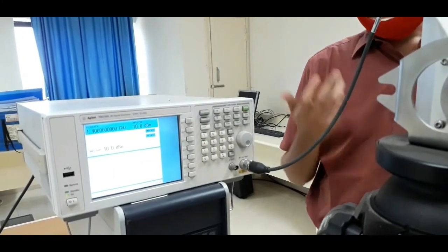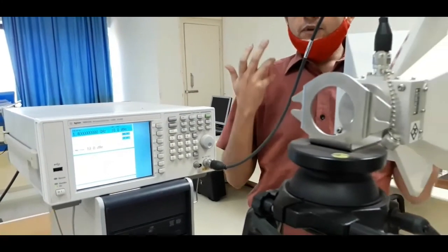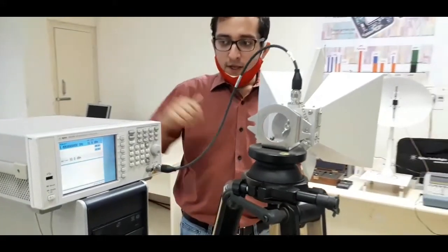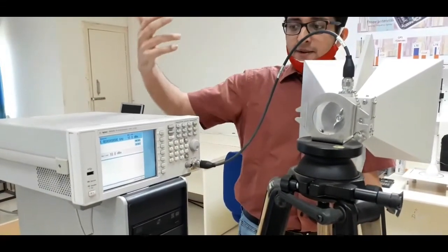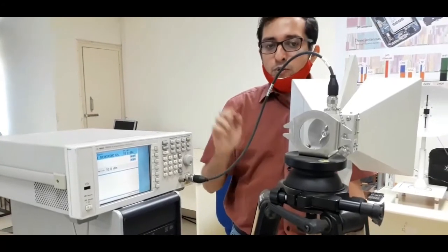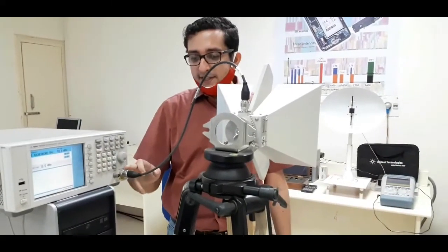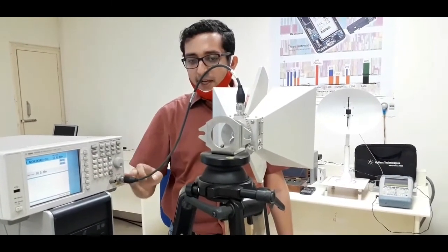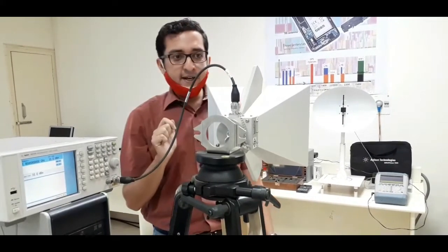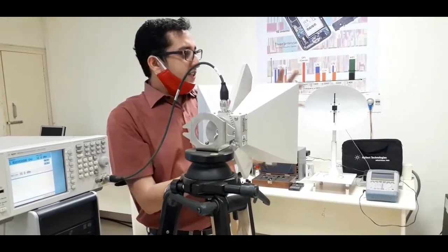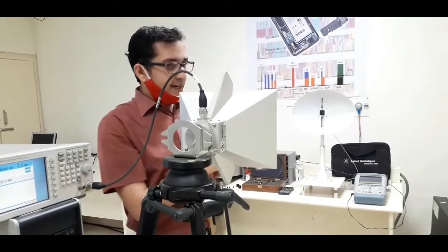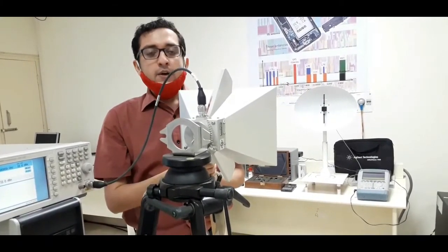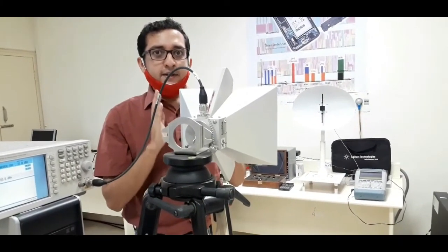Now what is dBm? dBm means power level with respect to 1 milliwatt of power. So if you use the logarithmic scale, 10 dBm would correspond to 10 milliwatts of power. What is essentially going to happen is that this 10 milliwatts of power will be fed to this transmitting antenna, and this power would essentially reduce in magnitude as it goes to the receiver. With this, let us look at the receiver setup.